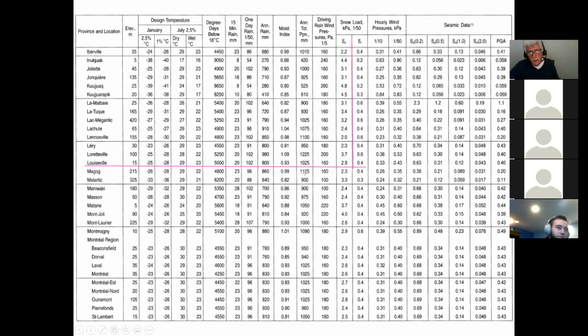And guys, when I go to the National Building Code and I look for these values, I take my ruler and put it right across here to make sure that I don't accidentally take 2.3 instead of 2.9. You understand? I try to be very careful, and I even sometimes double check to make sure I'm using the right values. So be careful about that because it's so easy. Oh, Louisville, 2.3. Okay, because you're just going across with your finger. So be careful about that.